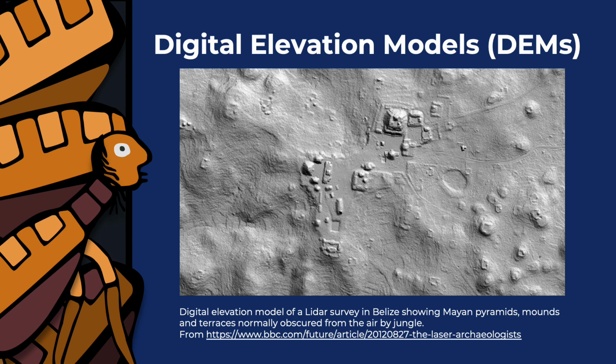There are two main ways of creating DEMs through UAV survey: photogrammetry and LiDAR. Photogrammetry is a process where computer software is used to identify thousands of common points in overlapping photographs to create a 3D model, through geometric intersection. The photographs are reoriented, warped, and mosaicked together into a single large image known as an orthomosaic.